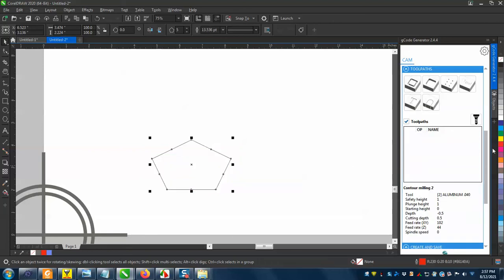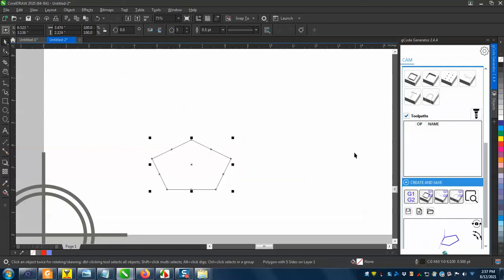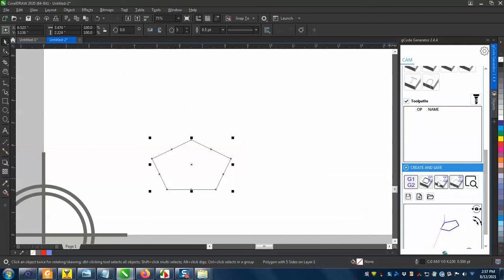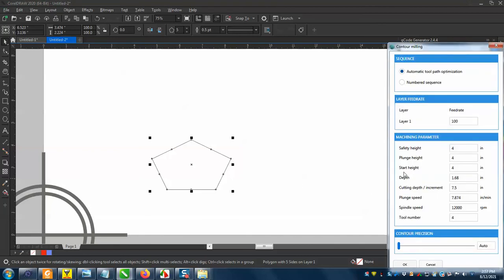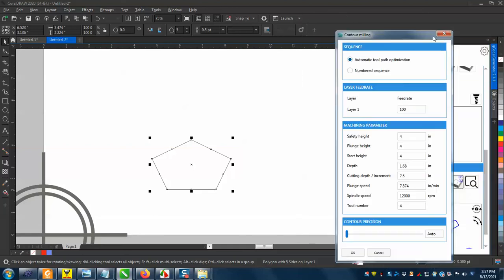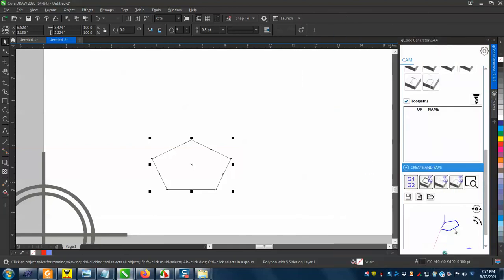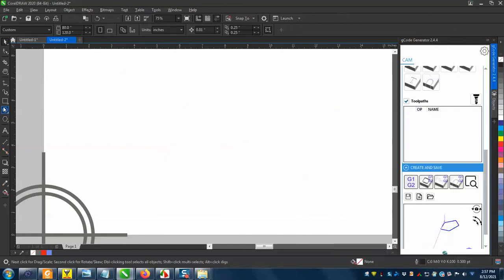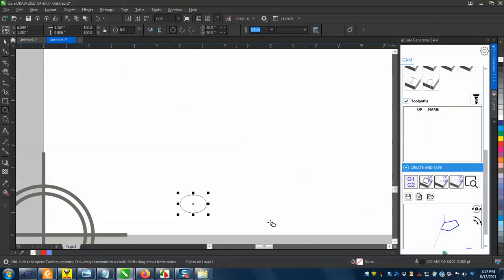The way these work down there is that you just select your shape, you don't do anything here, and then you click here, and it's going to create G-code. In fact, let me change it so you'll see a different shape down there that it is working. I'll do a small circle, so that way when it spits out the G-code, you know it did it for the circle and not for that old one.